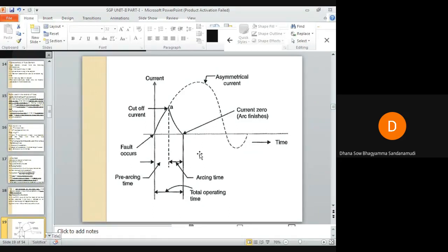The RMS value of the AC component of the maximum prospective current that a fuse can deal with at a rated service voltage is known as breaking capacity. Breaking capacity means the fault current interrupting capacity. The breaking capacity of the fusing element will vary based on its rating, the circuit to which it has been connected, and the magnitude of the fault current.